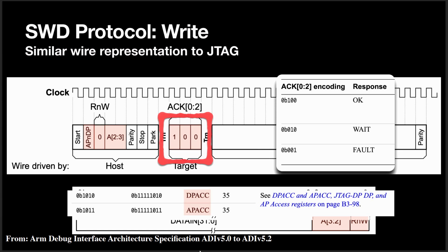But now instead of accessing a different JTAG address, we just have this 1 bit towards the beginning of the frame that sets the AP or the DP. So what they've done is they've taken everything you use as JTAG and just put it in 1 message that you send the target. Everything else just gets stuck in the data field. But everything else is actually identical between JTAG and SWD.